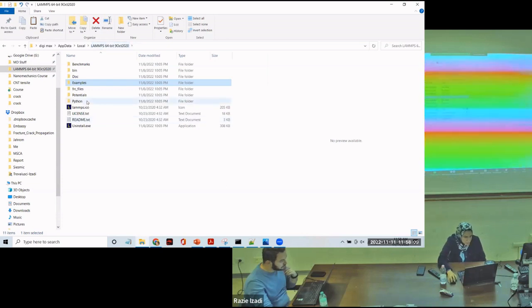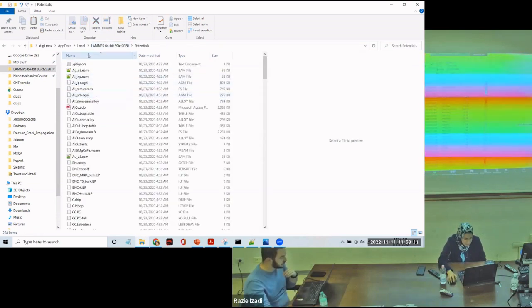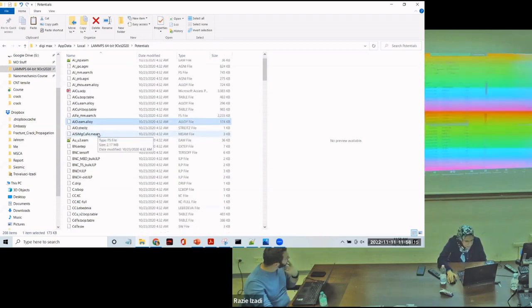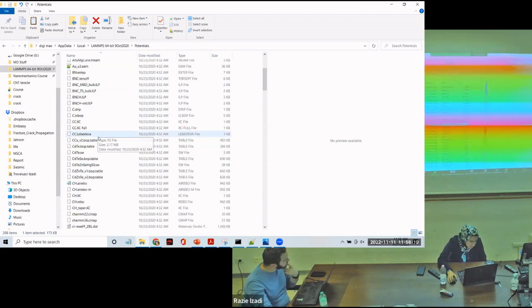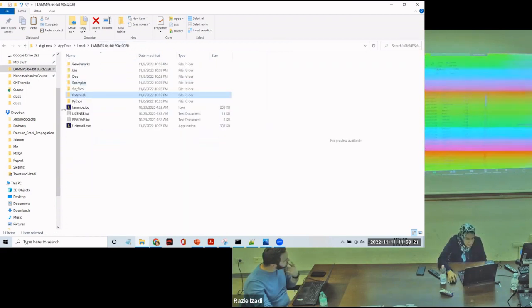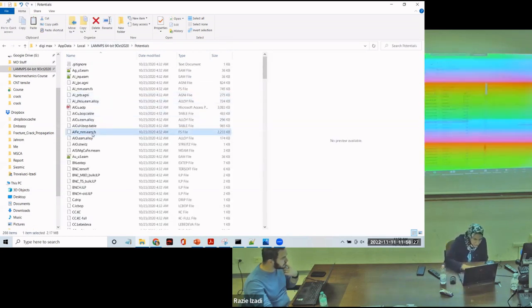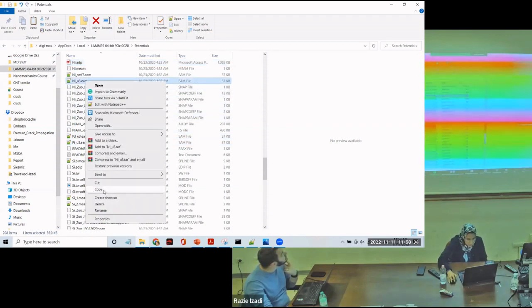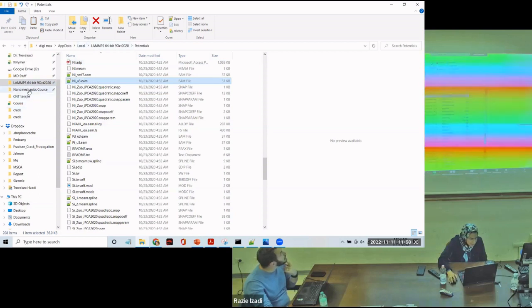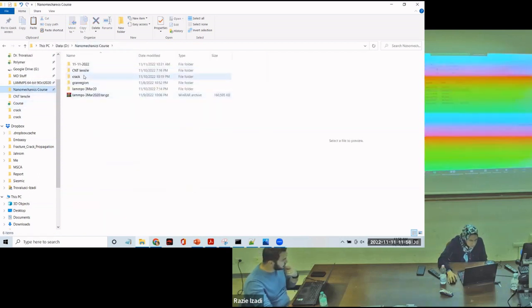Please just go to the potentials. The input file, sometimes it can get automatically, but if not, go to the LAMMPS folder that you have already installed, go to the potentials, and then find this file. This is what you're searching for. Just copy and put it in the folder that you are already simulating.